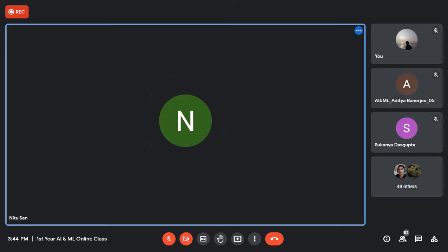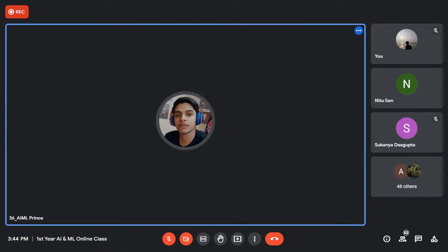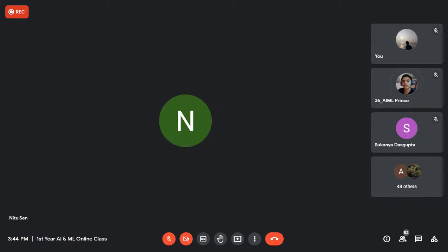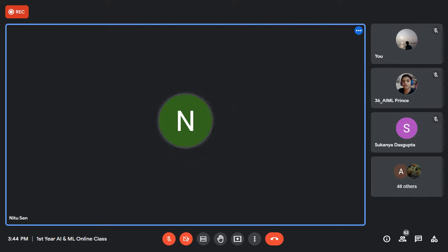Can you repeat that, ma'am? Rating: 1/2 ampere means if it is connected in series, then the current drawn is 1 ampere, and if it is connected in parallel, then the total current drawn is 2 ampere. That is why 1/2 ampere, comma, 3 voltages are there, 150/300/600 volt.